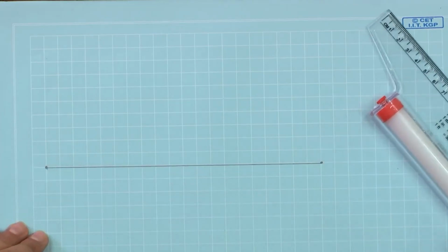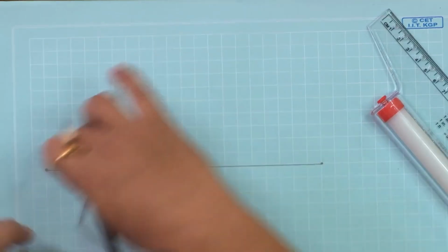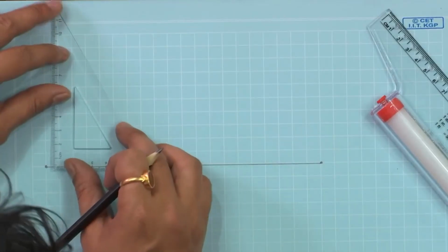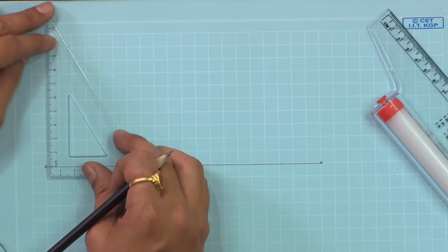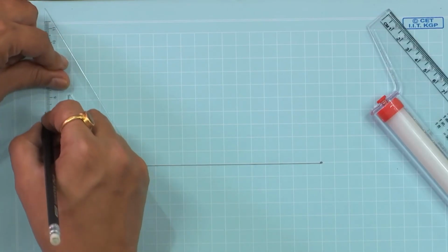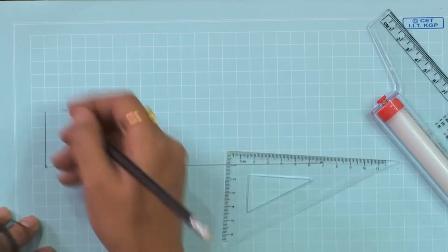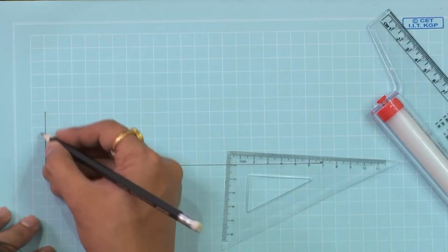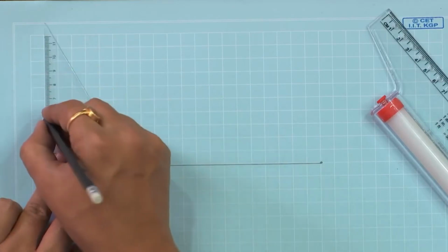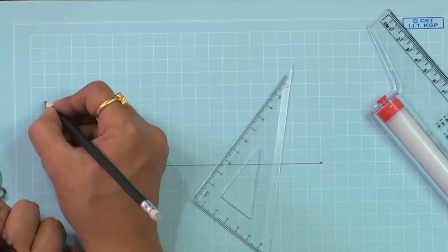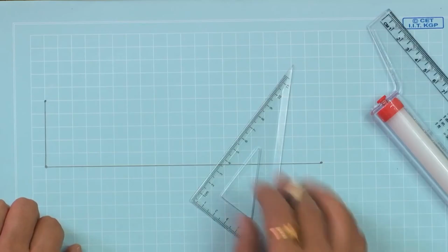Then vertically we have to go by 50 mm. So, let us use our protractor and mark 50 mm. First of all, we will construct the front view, the 50 mm object here. One, 2, 3, 4 and 5, up to this part. Then we have to construct a rectangle from the view.